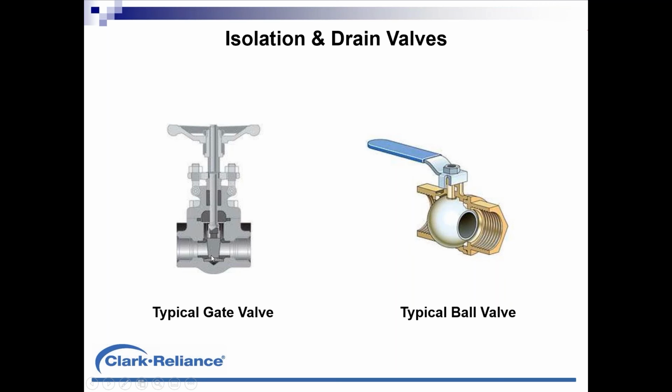So as a result, often in high pressure steam service, gate valves don't provide the service life that one would expect out of a boiler valve. Ball valves are permitted. The only concern about ball valves is it's hard to do a slow open and slow close if you're trying to be careful about putting an instrument into service and watching for leaks.